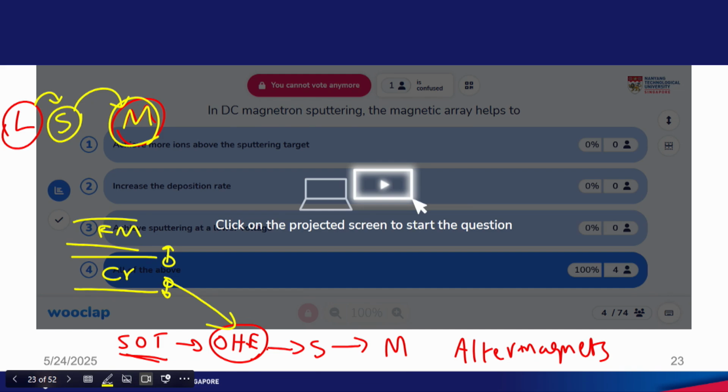So what we do, we use some materials like a thin layer of platinum. Okay. So platinum has heavy spin orbit coupling. So this is spin orbit coupling, right. So platinum can convert L to S. Because of this platinum, now spins are coming into the ferromagnetic layer and they can switch magnetization.